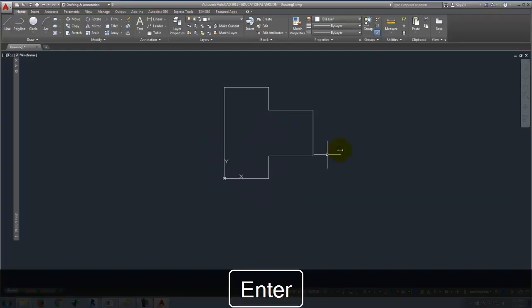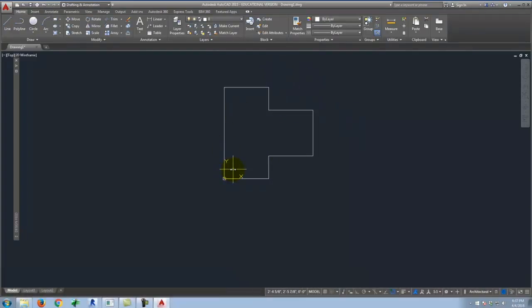Okay? So we've gone through and we've talked about absolute coordinates and relative coordinates. And there are times where you really want to use these because it's convenient. You know where the line wants to go, and you can draw it that way. There is, however, something called dynamic input that is aimed at making your life a little bit easier. And so at this point, we're going to turn that button for dynamic input back on. And now that it's back on, we're going to start drawing again.